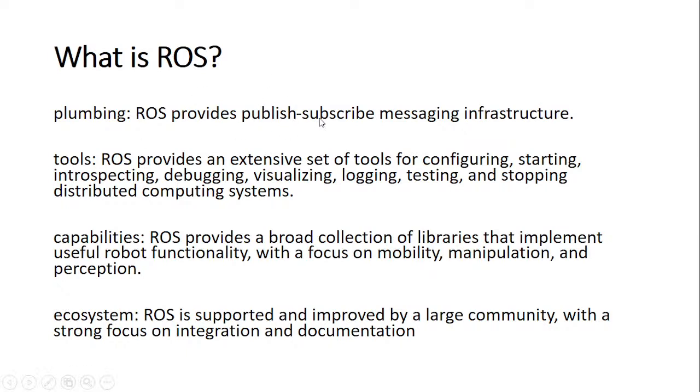If the microcontroller needs to get the velocity values whenever it needs to move, it can subscribe to a topic. The publisher, the single board computer, will be publishing the velocity data using that same topic. So if the microcontroller subscribes to that same topic, then it can receive all the velocity values coming from the single board computer.